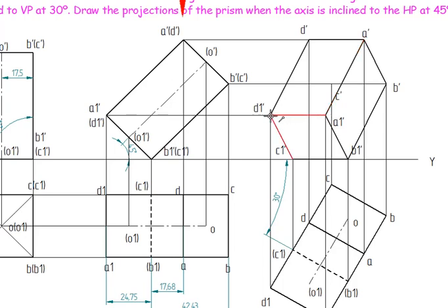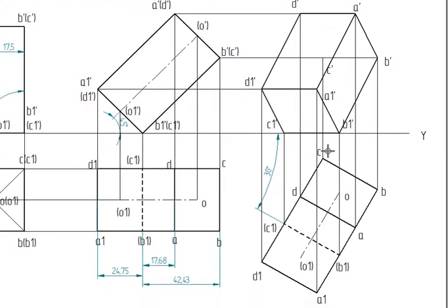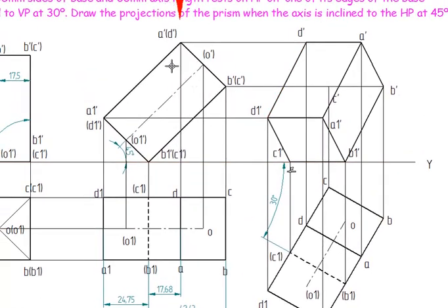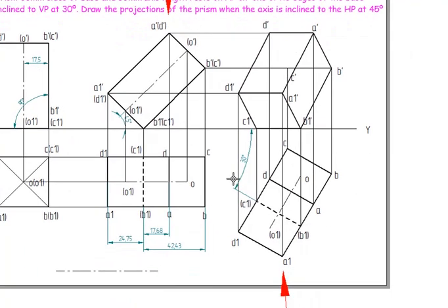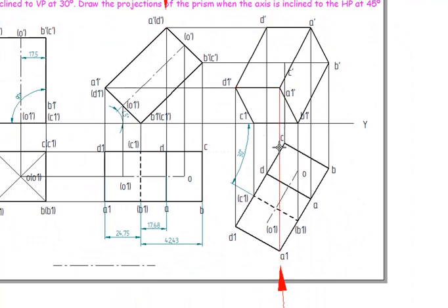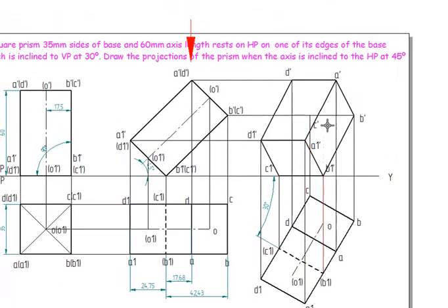The next thing is, as an observer, here the farthest point for an observer was B1 C1, so it was in dotted lines. Similarly, the farthest point for an observer is C. Nearest point is A1, farthest is C, so line joining C must be in dotted. So that means from C it is joining to D, C is joining to B, and C needs to be joined to C1. So it is joined.